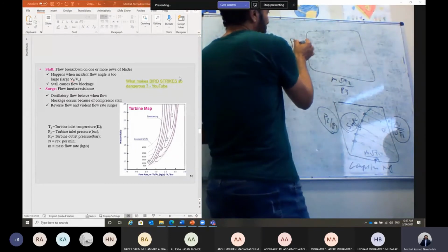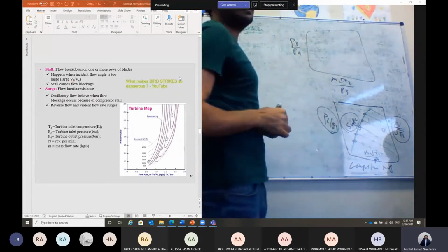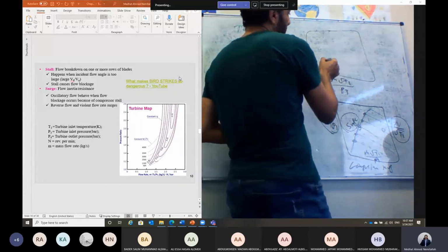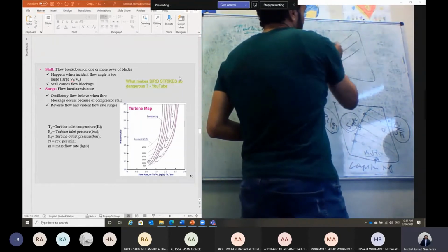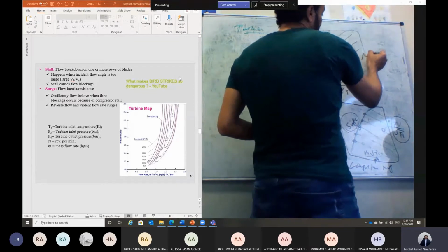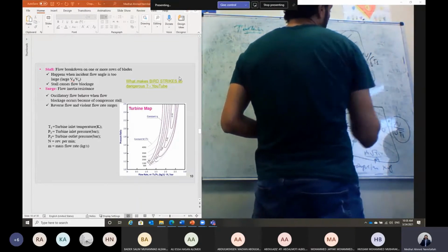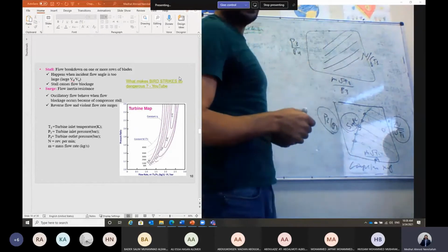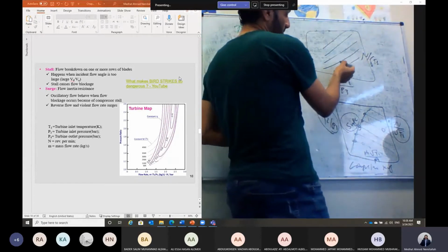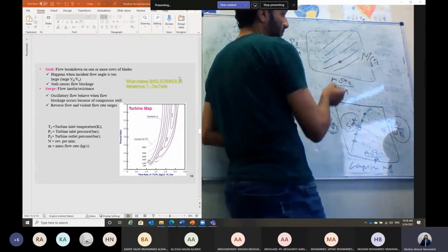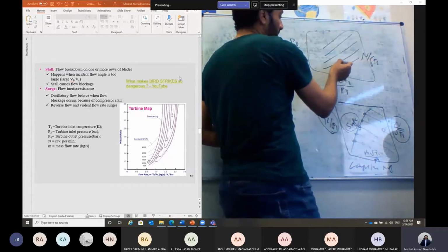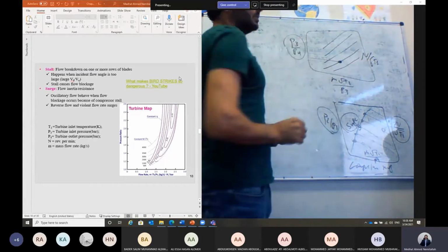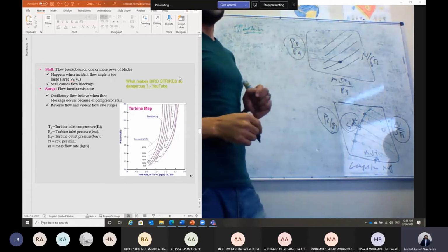And here is the pressure ratio of the turbine, which is P3 divided by P4, and different values, guys, of the running RPM, N divided by square root of T3. Different values here can actually give you the operating point. So if you have, let's say, through the turbine a given mass flow rate at a given RPM, then in this case, we can calculate the pressure ratio of this turbine using this map.